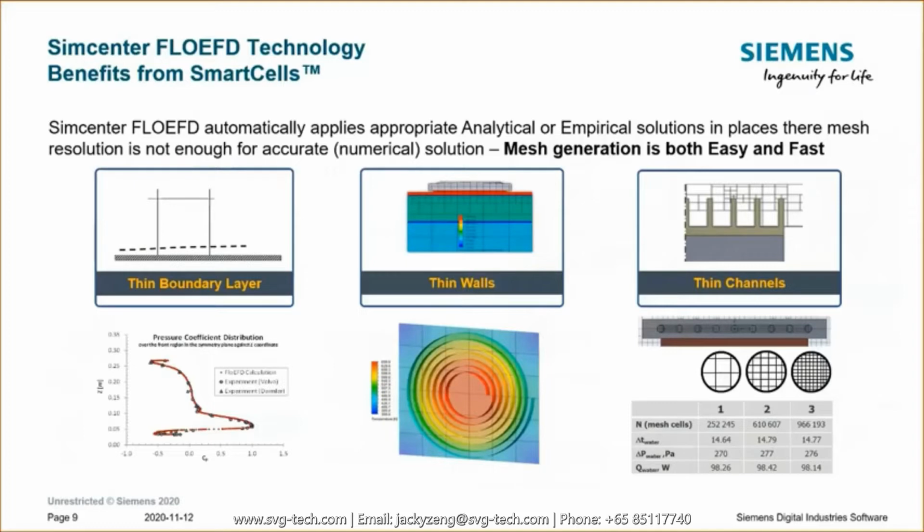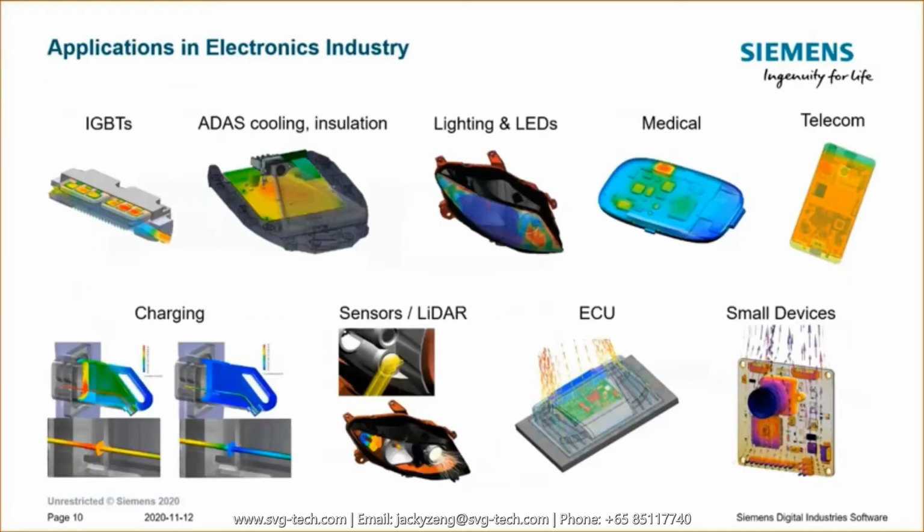So we incorporate some innovative modeling to handle things like how the boundary layer is treated and areas where, let's say, the mesh is coarse relative to what you would classically need in CFD. So this is all being handled by the software in a somewhat transparent way, allowing both the speed to get through this process that you desire, as well as opening up to more people being able to do this type of analysis. So that's FLOEFD and front loading generally.